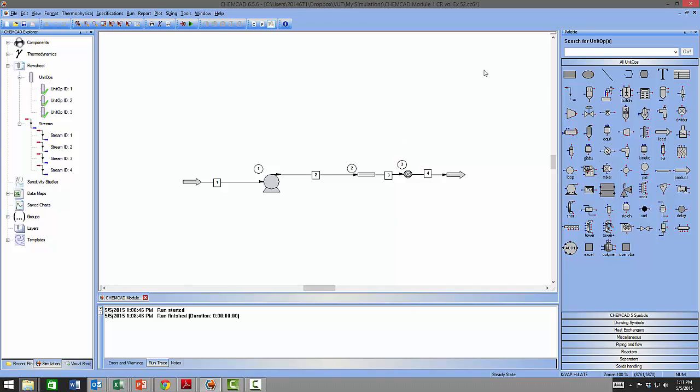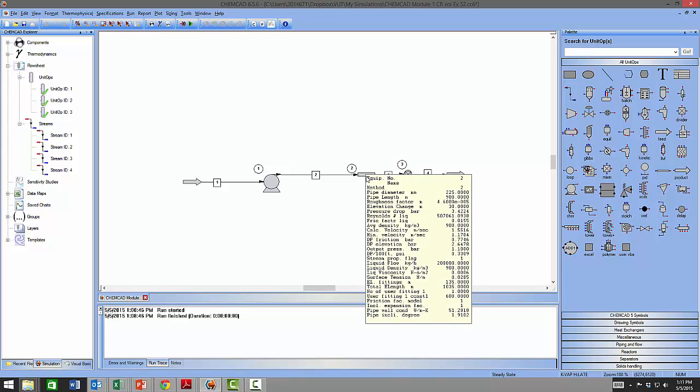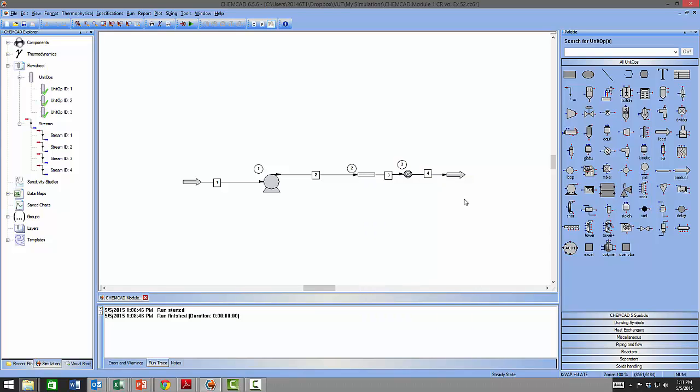We did not do trial and error. We used the controller to target the pressure that we want stream 3 or 4 to be at, and then we manipulated the power output or the outlet pressure of the pump to only overcome the pressure drop due to friction, and then also elevate the pressure from 1.05 to 1.1 bar.